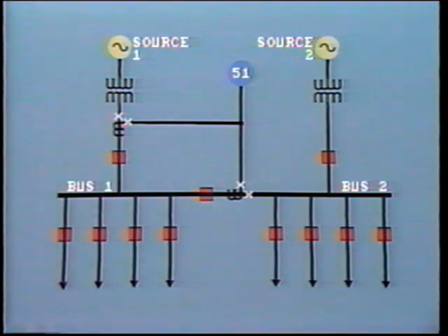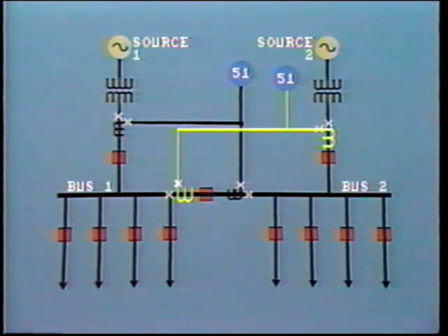This protection will also operate for a heavy fault on a bus 1 feeder which fails to be cleared by its own breaker. The system therefore operates as backup, and the setting of the relay must allow for this. Of course, a similar pair of CTs will be connected to provide partial differential protection for bus 2.